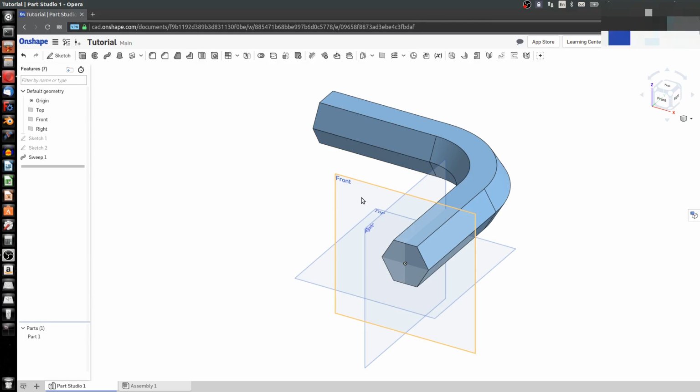Now for any feature, whether it be an extrusion, a revolve, a sweep, or anything else, one of the largest features of parametric modeling is just that. It's parametric. We model around parameters. And should we want to redesign, we can always go back and make a change. So here's my history tree of everything that I've done on this particular part. I've created a sketch, which is what is highlighted in orange. I've created a path, which is also highlighted in orange. And then I've created the sweep.